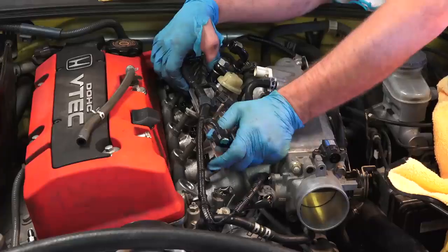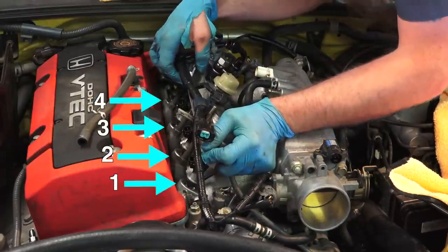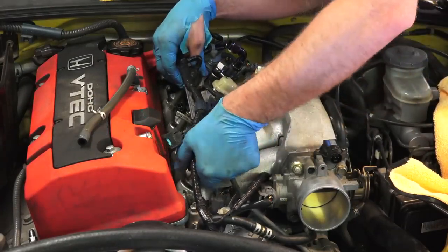Now, some of the earlier fuel injection designs actually had the injectors right at the throttle body. However, the disadvantage here was that it actually had varying air-fuel ratios across the different cylinders. So typically what you'll see today is at least one individual injector for each individual cylinder so you can directly control the amount of fuel going into that cylinder.